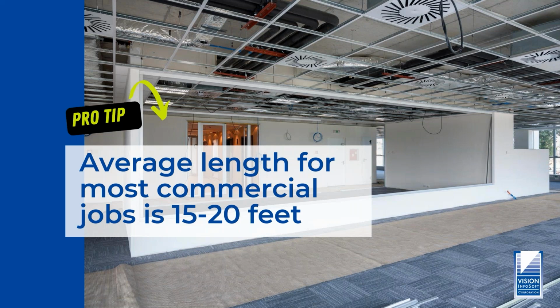You have to adjust for anything else that's just common sense. If you've got two receptacles up on a roof, you can't use this formula. But if you've got a typical commercial office space like this, a school, even a retail space, this 15 to 20 feet works pretty well. Now, that does not include home runs. Home runs are a whole separate thing.